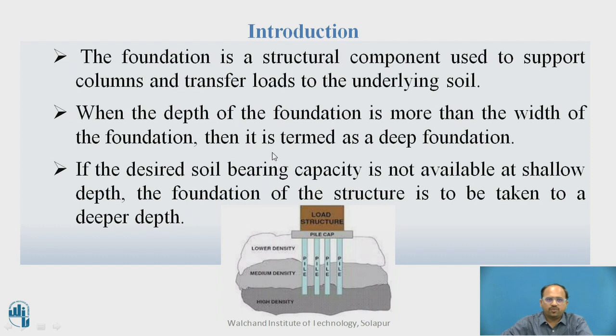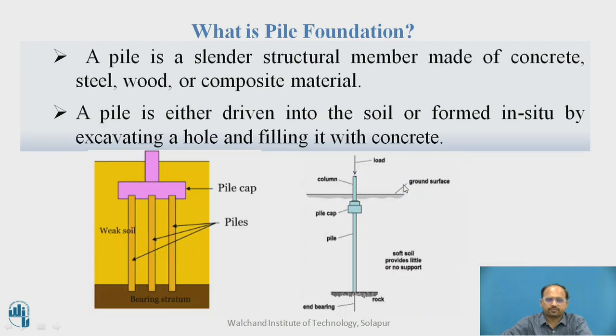Introduction. The foundation is a structural component used to support the column, and that load is transferred to the underlying soil. When the depth of the foundation is more than the width of the foundation, we call it a deep foundation. If the desired soil bearing capacity is not available at a shallow depth, in that condition we will go to a deeper depth.